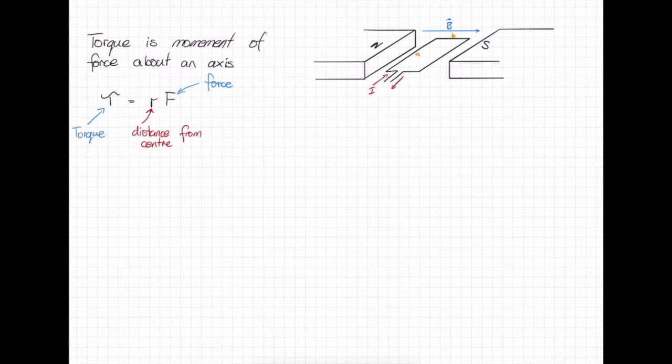So if we look at this, we also know that our force, due to our right-hand rules and our knowledge of electromagnetism, is going to be the perpendicular component of it. So that's going to be equal to RF sine theta. So as our wire rotates up, we're going to get a perpendicular component of our magnetic field. So that part there is going to give us a theta component. So it's not 100% in the magnetic field, so we only get a component of it.